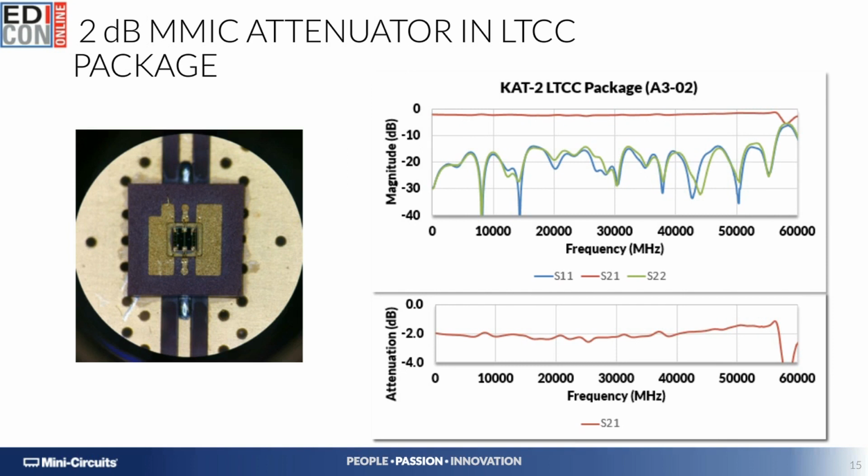We quickly notice that the insertion loss performance is pretty flat. It's around 2 dB all the way up to 55 gigahertz. And return losses are close to 15 dB or so, all the way up to the same frequency range. This is an impressive result, and we're very proud of it.